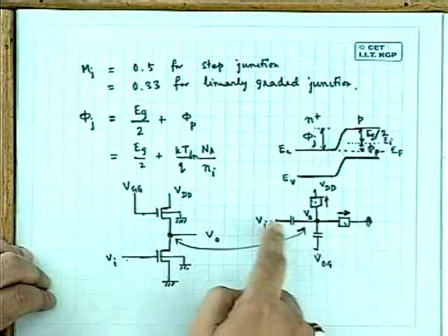And along with that, if you know the values of the capacitance, it is now possible to calculate. First the DC analysis. To do the DC analysis, the capacitors do not come into the picture. Then you do the AC analysis under small signal condition, which is rather simple, as indicated earlier. In that case, time can be considered harmonic, so all d/dt, etc., can be replaced by j omega. A very typical technique. And the third is the large signal transient analysis, which is very important for digital applications, which is most complicated. And for that you cannot use any analytical approach.